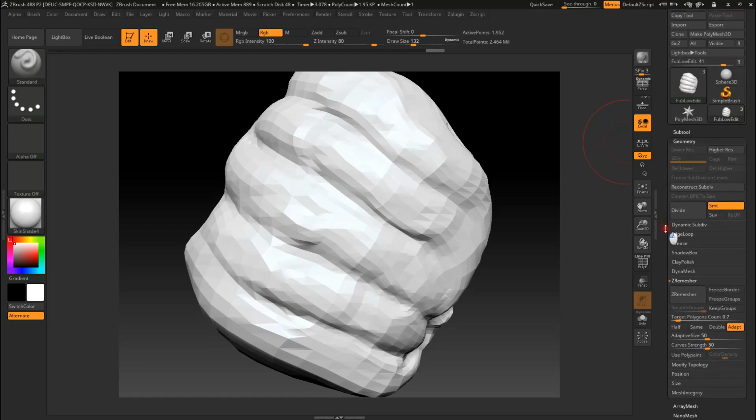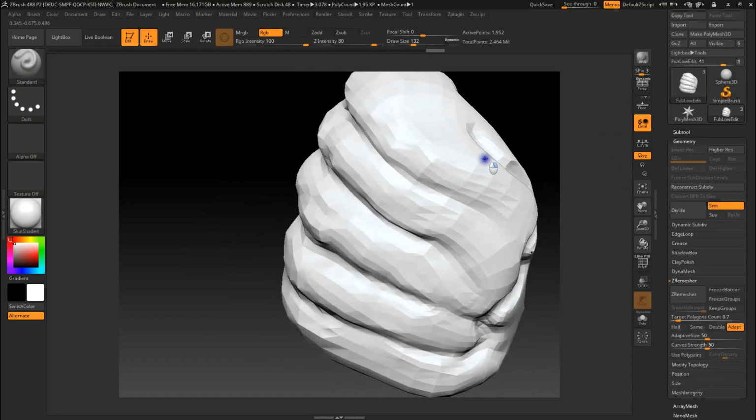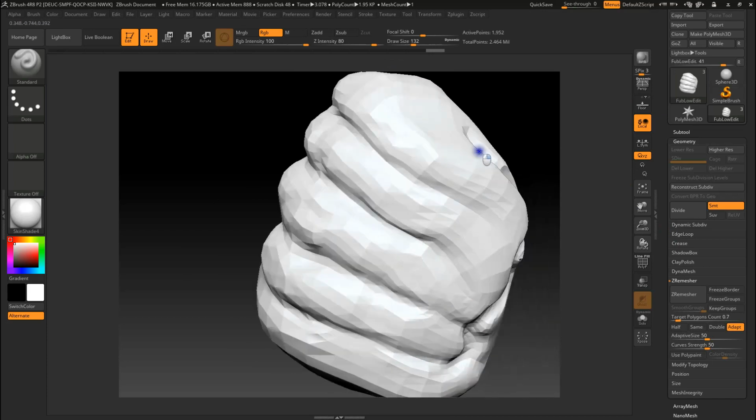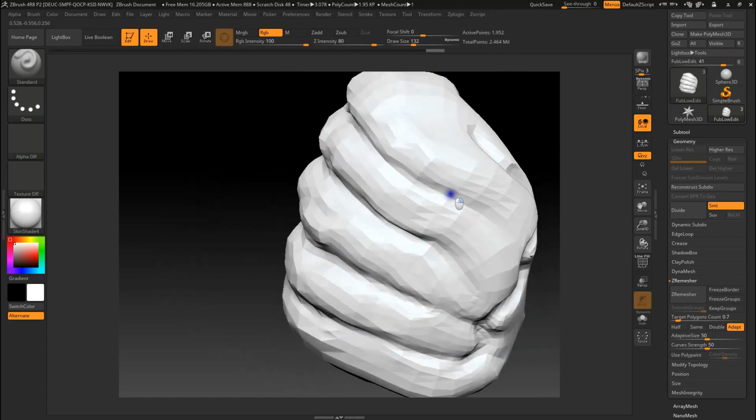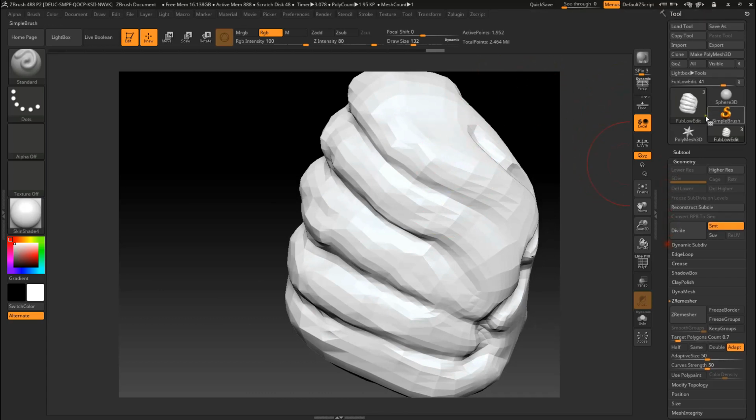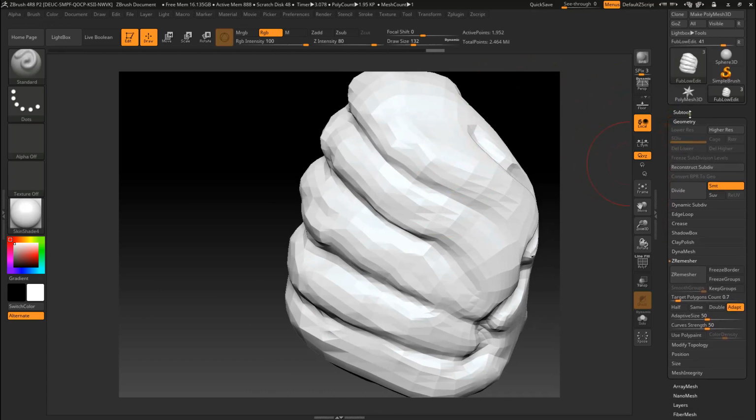And what we're going to do here is create some subdivision levels on this simple geometry, so that when the normal map projects to it, we can use that. We're going to project some of the detail from the sculpted version onto the higher subdivision levels, and then we're going to project the normal map based on those.